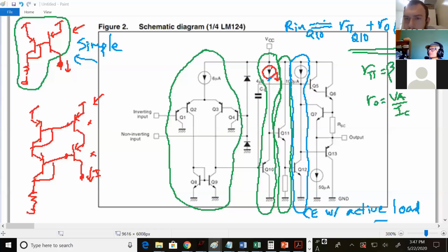Oh yeah, currents. I think so. I think that Q5 and Q6 might be increasing the current from the 100 milliamps a lot, because you'll go into the base and then to the emitter, it'll be 1 plus beta more, and then it'll be 1 plus beta more after Q6.